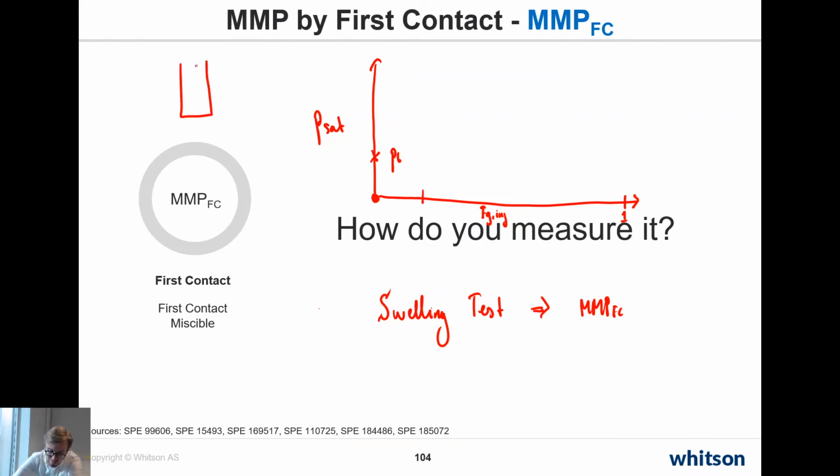Then you go in and take that reservoir fluid and mix it in the PVT cell such that Fg is equal to, let's say, 20%. That means the moles of the injectant in that cell versus the total number of moles in the cell, if you do this fraction right here, you should get 0.2 or 20%. Then you take this mixture and do a CCE experiment to measure the saturation pressure, and maybe we get a second bubble point, but this time it's a little bit higher.